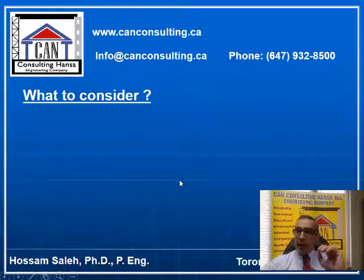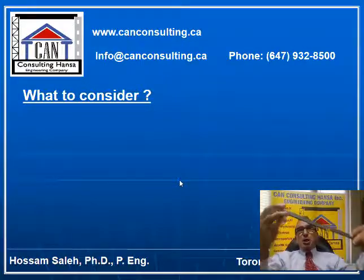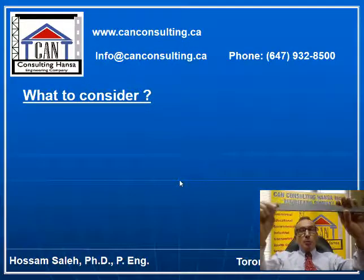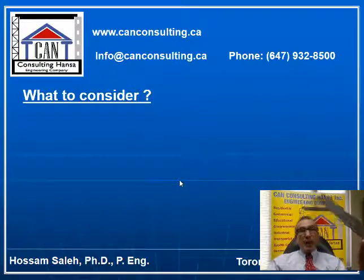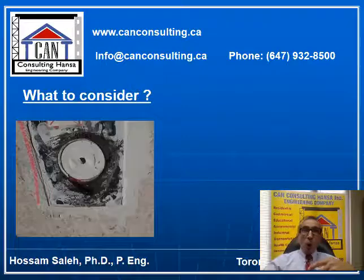And what we have to consider here are many things. One is the end connection. The end connection of the FRP is very important, and you have different details for that. And also you have to provide fire protection, because that's one of the disadvantages of the FRP. And what else do we have to consider? You can't mix the products from different companies. That's very important. You have to check the warranty with the applicator or with your company.